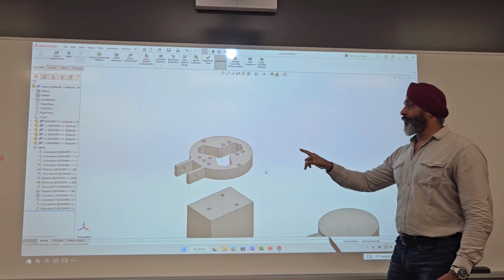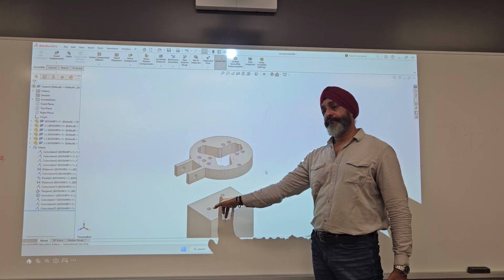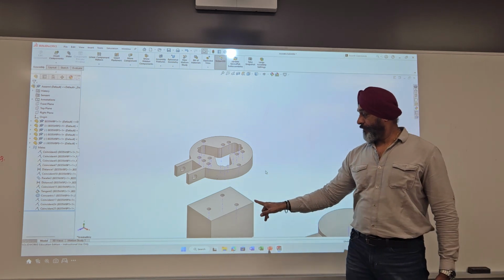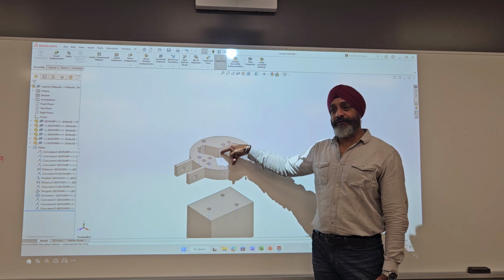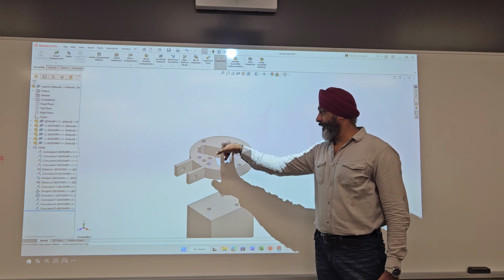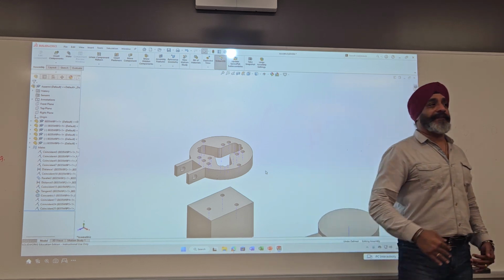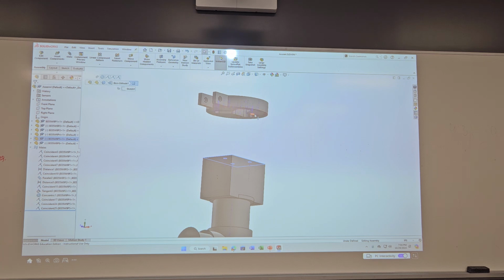Get that? These two holes to these two holes. Okay? What about the third one? Third one you don't need it really, because once the two bolts are there, it can't change. Okay, you can make the third one too. These two are minimum. These two, and then make the faces so that it will sit on top of each other. Mate, and mate.